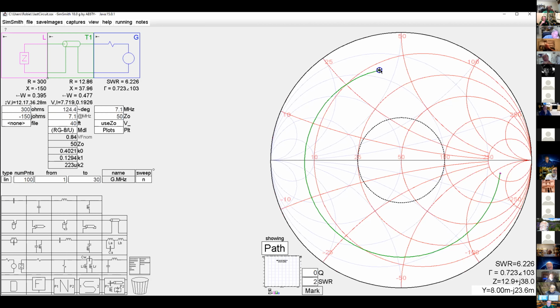So there are a lot of things that can cause the SWR to be 10, and some of them the tuner can't handle. So let's say I'm here at 12.86 ohms, and maybe my tuner's having trouble matching it on this band. One thing I can do is add a length of transmission line to help raise this impedance value a little bit. It's not going to change my SWR very much, but maybe it'll get into the range of what my tuner will handle. I haven't done that yet, I'm just going on the fly here.